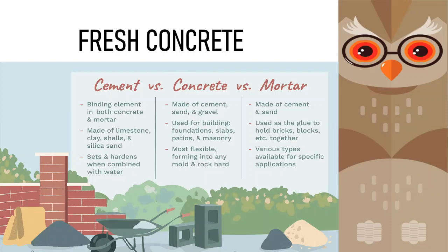The purpose of cement is to hold the other materials together, but you can't just use cement alone. You need the other materials, and what you mix with the cement will determine the final product. These are ground into a powder and gypsum is added, creating the grey flour-like substance known as cement. When water is added to cement, it triggers a chemical process that allows it to harden. There are many different types of cement, but the type most commonly used in construction is Portland cement.